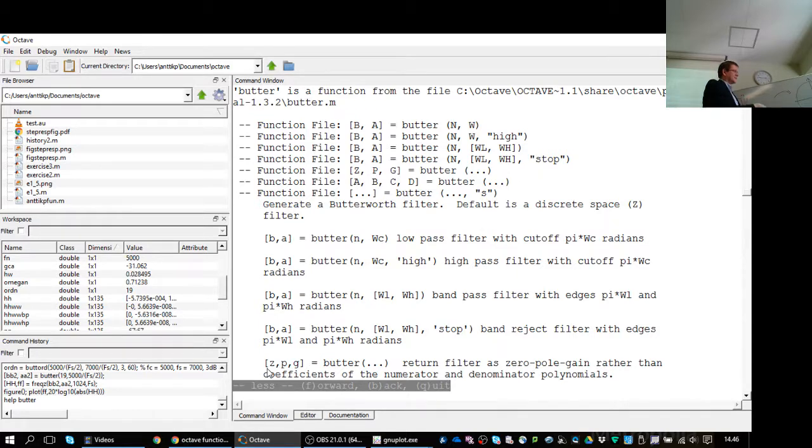So think of a system which is FIR. If you modulate just the numerator, it does something for the zero points. It just moves them to a different place. Same thing actually if you have poles here. If you modulate, it moves them also around that modulation frequency. So practically, the band-pass and band-stop and high-pass are just doing the modulation there.